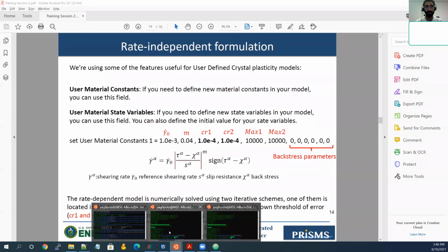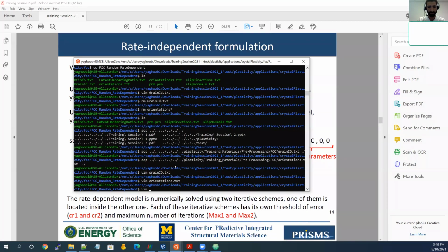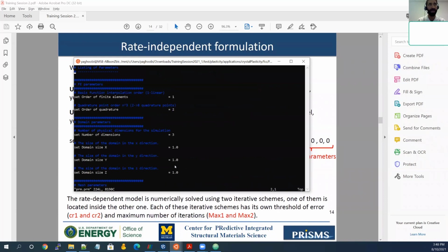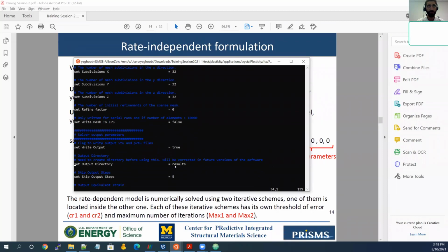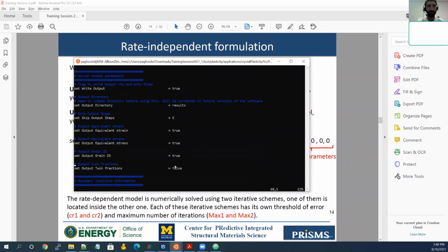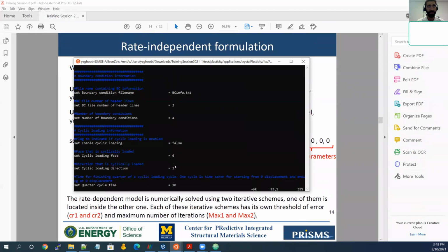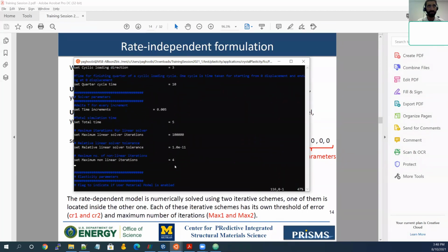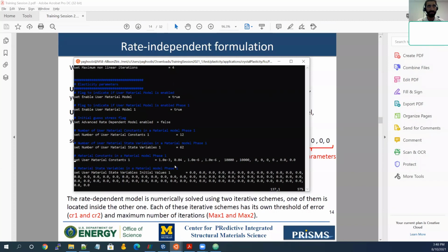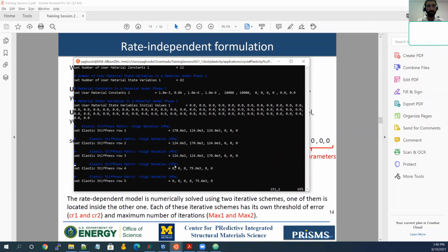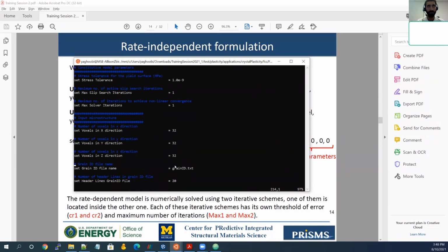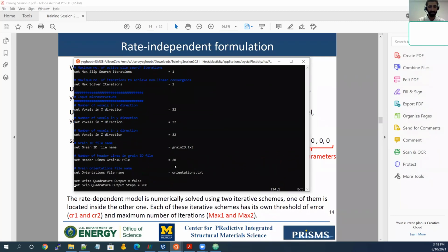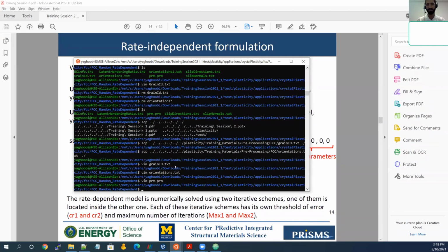within that folder. So if you open the PRM file, just to double check, now you should have 32 by 32 by 32 true results every 5 increments. And the parameters, these are updated. And these are the rate dependent constitutive model parameters. And all the other parameters are the same except the input microstructure, which I updated. So I can just start running the simulation.